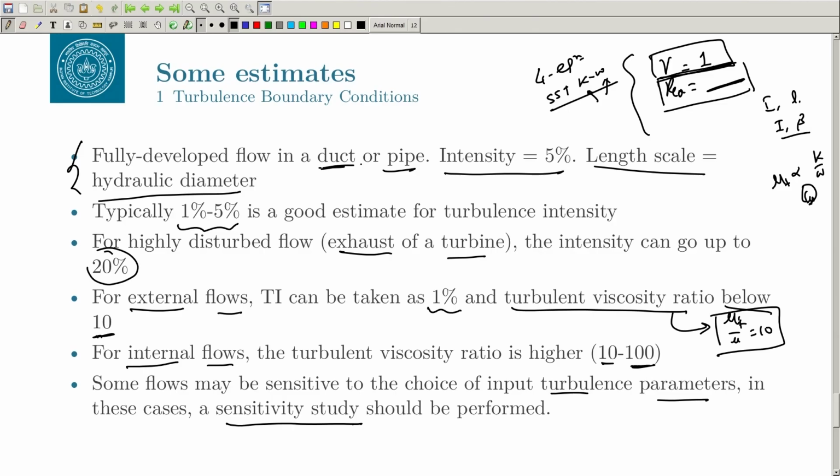If you take, for example, the flow over a turbine blade or a compressor at relatively low Reynolds number, maybe the transitional Reynolds number, where the flow is transitional and there is high curvature on the turbine blades, and then you have a lot of disturbance because the flow that is coming in is from another turbine, they are highly disturbed.